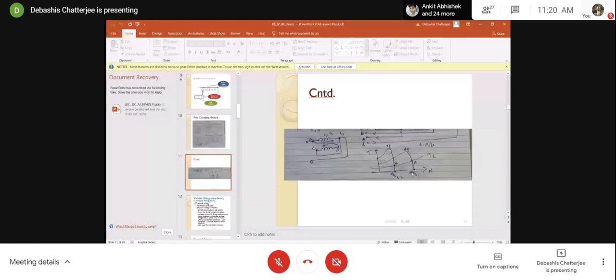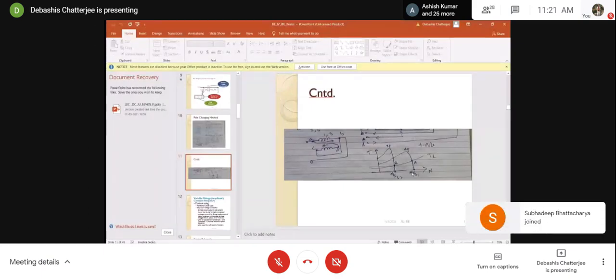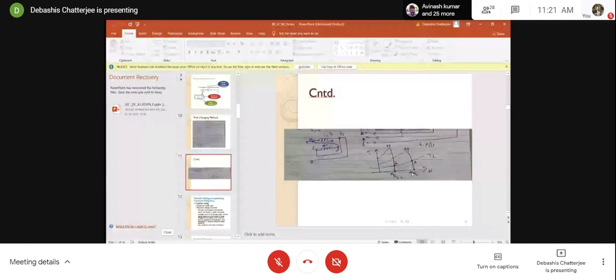Then after that, this type of speed control was not really applicable to slip ring induction machines, because to have successful, steady torque production, the stator number of poles has to equal the rotor number of poles.